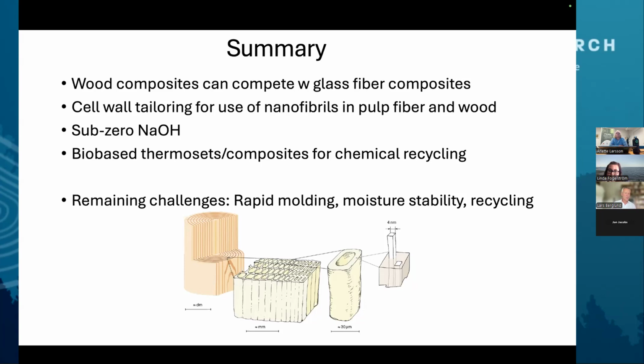Okay, so it could not be beneficial that, for example, you have a reaction between your cellulose and the polymer, and then under certain conditions you can revert it and make it recyclable this way? I don't know. Yes, I think that's not a bad idea. It has been explored substantially for nanocellulose composites, because the nanocellulose fibril is not accessible for the polymer matrix. So in that case, people have worked on that concept, and there it makes more sense.